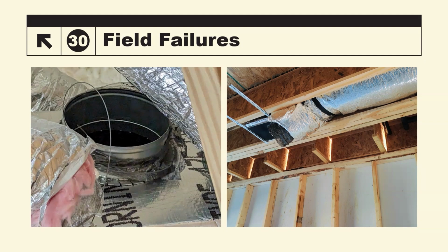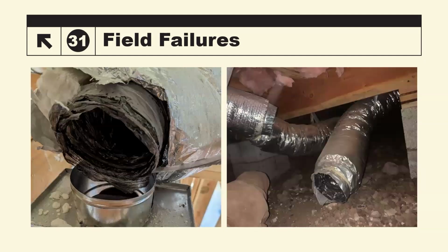So just QA, QC, looking at the field work and looking at contractors and making sure that those guys are doing it. It doesn't mean the company's bad. There may be one guy that just got hired that came from a different company, and that's kind of how he did it, which is the same thing we see here. Again, mastic all over the duct, nothing on the collar. It looks sealed from the outside.